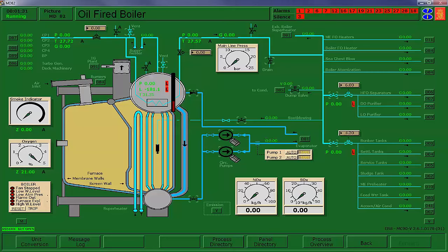We'll go ahead and open our air cock, and this you would close once steam pressure is raised and you see steam coming out of this vent. The air cock is there so that steam will push out any atmosphere within the steam drum, so that O2 does not get included into your boiler water. We're going to open our desuperheated steam stop 100%.